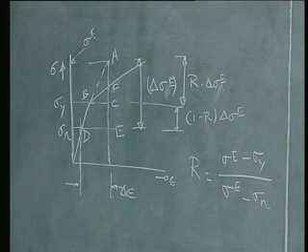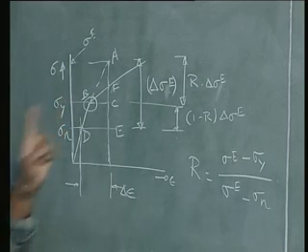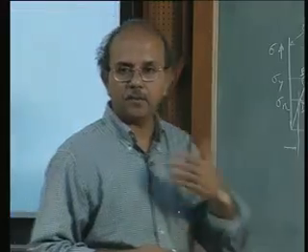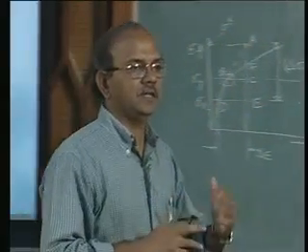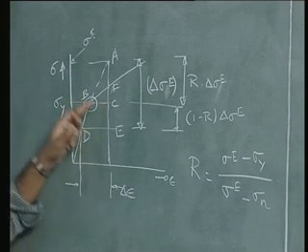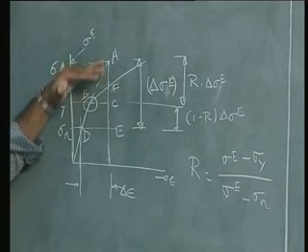One of the most important things that you see here is that I calculate where I hit that yield point. In other words, I recognize that I have crossed that yield point and I calculate where I hit it. So this is going to be a major step when I extend this to the multi-axial case, in which case I will have a yield surface and I will also look at where I cross the yield surface.